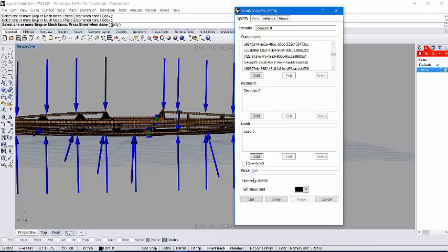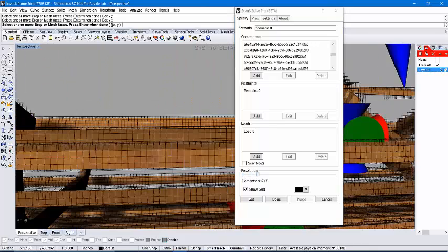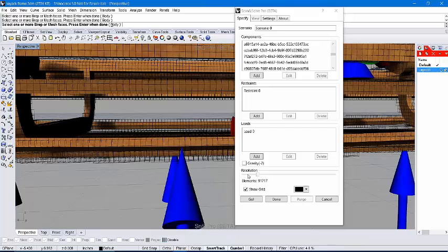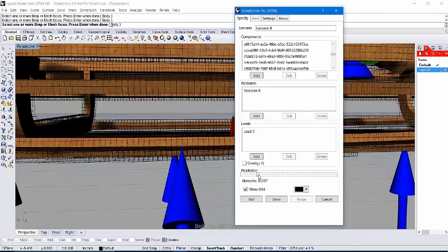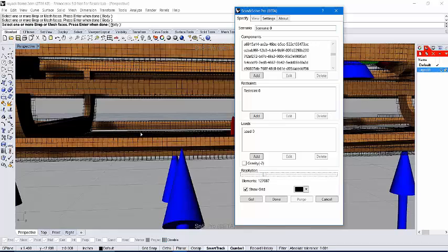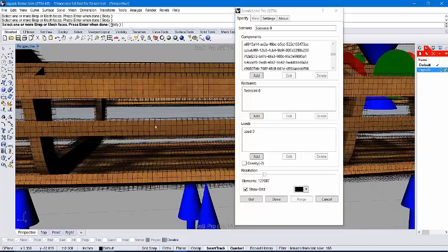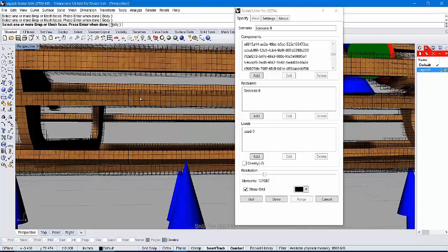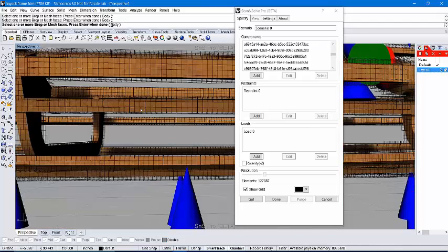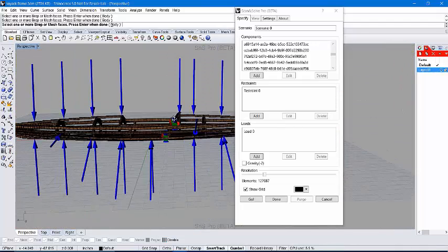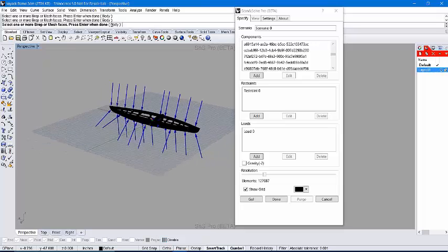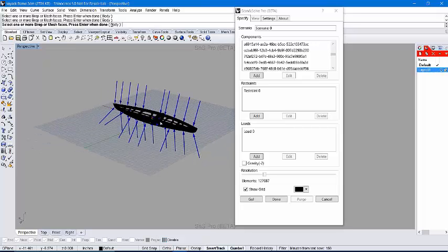Okay, it looks a little bit low still. Yeah, so right around here looks pretty good. You can see most of them have at least 3 elements. If some miss, like this maybe is 2.5 only, that's okay. It should still give good results. And you can also test for convergence. There's a blog post on that on the Scan&Solve forum as well to help you do that. But this is a pretty safe rule of thumb. So I'll turn off the grid.